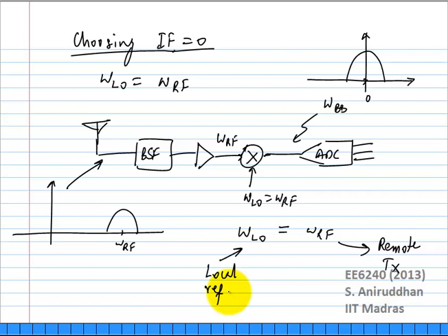Okay, you can decide what kind of specification you want, and then eventually, like you said, you will have to look at the baseband signal and calibrate out this frequency error. But suppose that is taken care of. Anything else? Suppose you are able to calibrate this out at the system level. So obviously this needs your processor to get involved to keep track of what the phase of the signal is and adjust the frequency. Anything else?